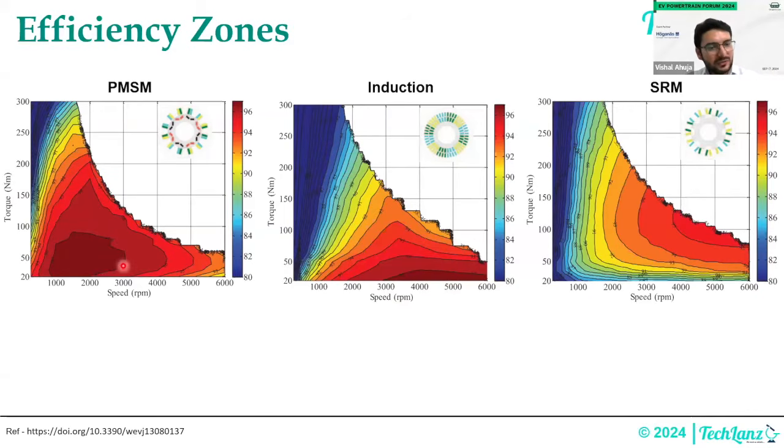And the PMSM motor offers you a wider band. Now, when you are trying to get a motor, if you're just asking for the max efficiency, you will lose out, because the number will look the same. What you are looking for is a cycle efficiency. As I talked about, two-wheeler, three-wheeler and four-wheeler applications are different, so based on your application, you have to decide what your cycle is.